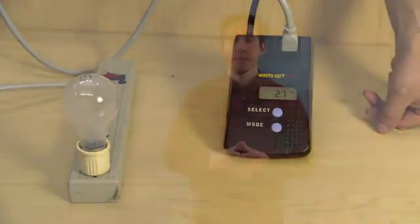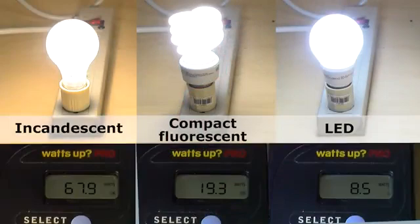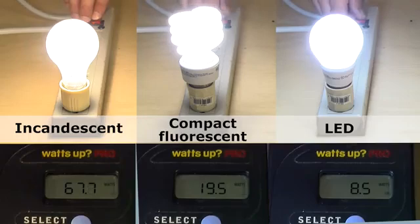I can then use the same meter to compare 3 different light bulbs: an incandescent, a compact fluorescent, and an LED. And we can see that for almost the same equivalent brightness, the incandescent bulb uses 67 watts, the compact fluorescent uses 19.5 watts, and the LED uses 8.5 watts. This also illustrates how switching to more efficient devices can reduce the overall energy consumption.